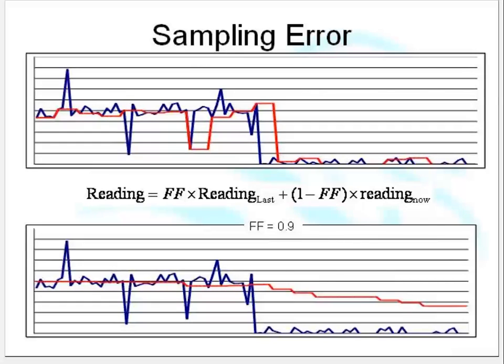The problem with noise is, if you just have this intermittent noise, with an ADC, because it samples, it can pick up a bum reading, and then it holds that reading for the entire sample period. A normal analog system would say, oh yeah, it's a bum reading, and just immediately see the next reading and not take any notice. But an ADC going into a PLC will see a bum reading and hold that bum reading for the entire sample period.